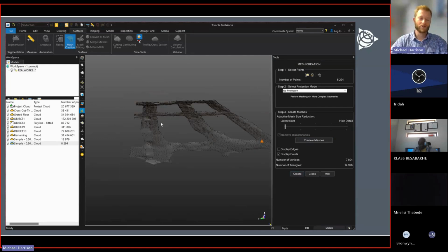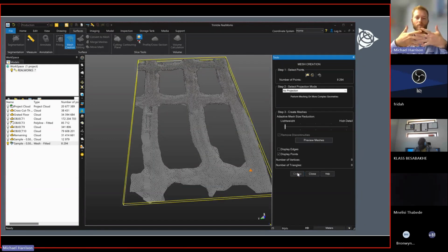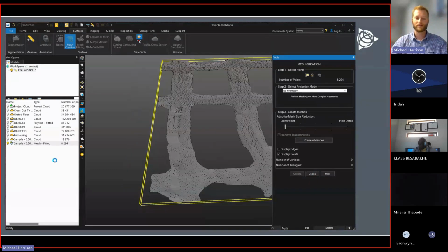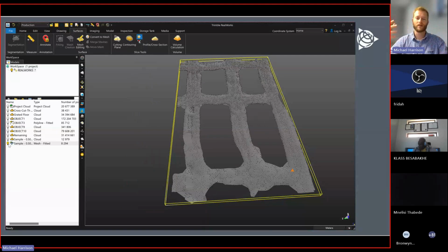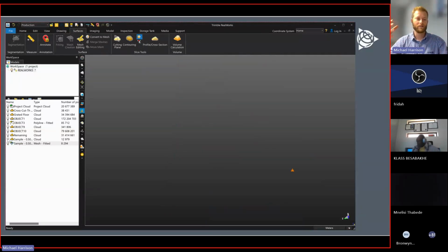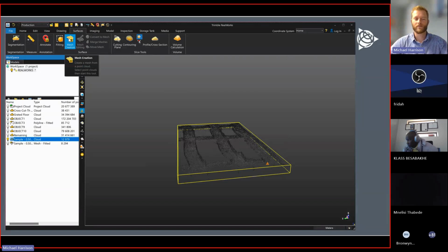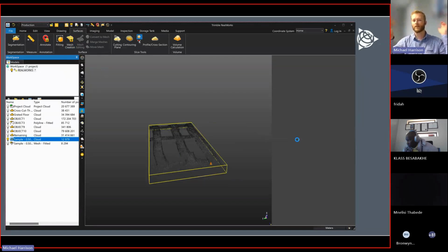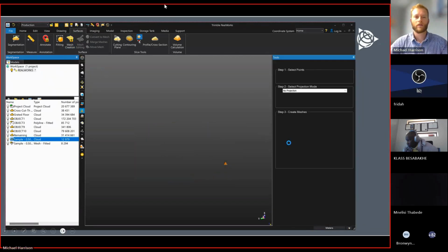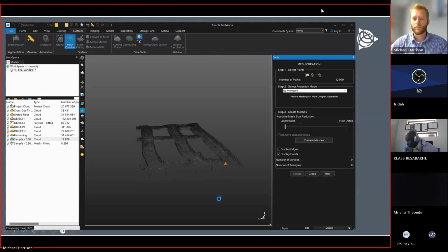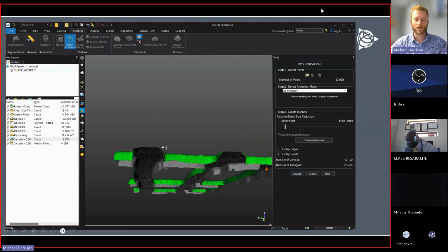But as we know, a mesh is a triangular mesh through our points, so if there are small gaps, it's just going to mesh through them. It's not completely critical to fill every single gap. And now we have the ceiling and the walls. This was a more consistent cloud, as there was nothing in the way. So now I'm generating a mesh.